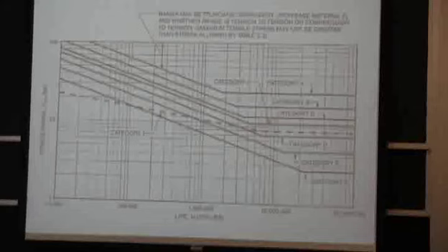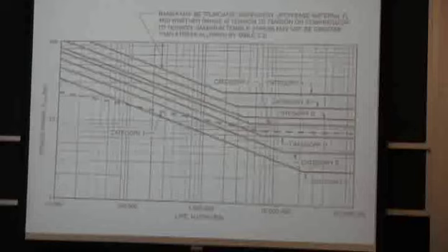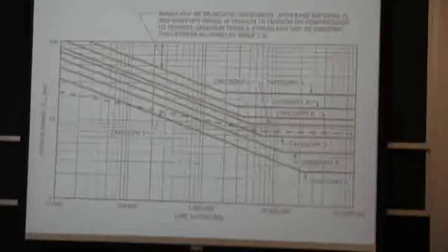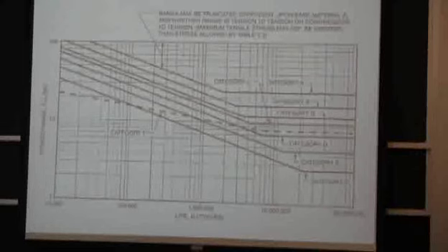Now this has all these safety factors built in, but you can see the difference between having and not having a weld if you're going to have a lot of cycles. We say a lot of cycles because here we're already at 10 million. So if we go to 1 million, we're capable of taking 6 KSI. So think of a weld as a super taxation on your design if you will have cyclic loads.